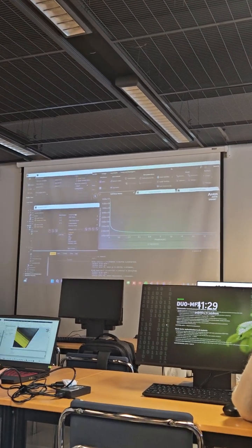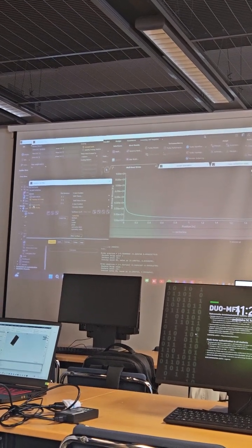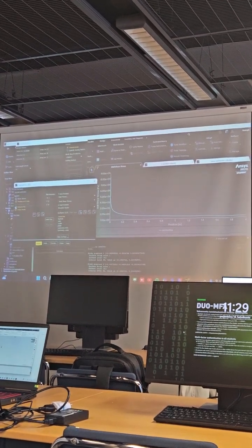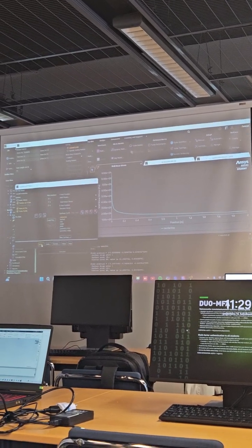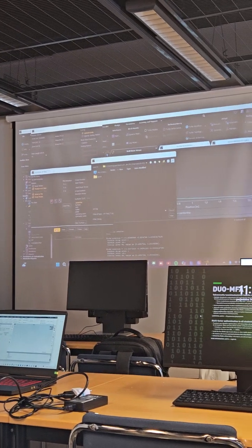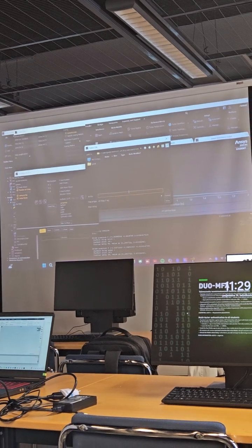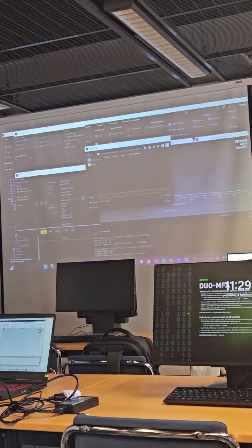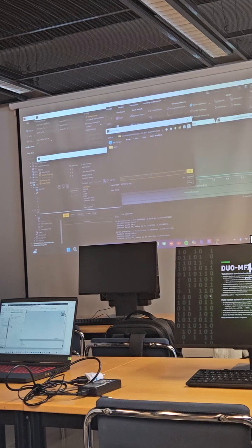We also need to post-process this, so we can actually save this file. And we can do that always in this window. You can use write to file. If you select that, there instead of save plot, now you have this write. So now we are in the working directory, the working folder, and we can save this distribution: tau wall shear stress over x, and we call it tau underscore w, so tau wall.